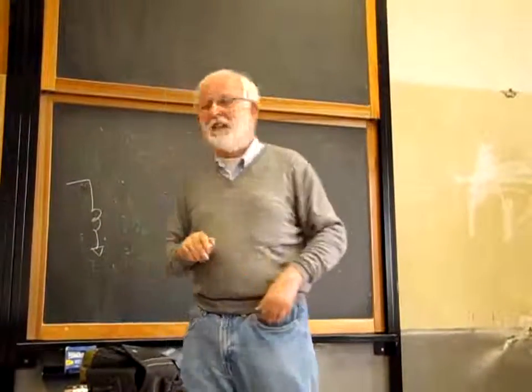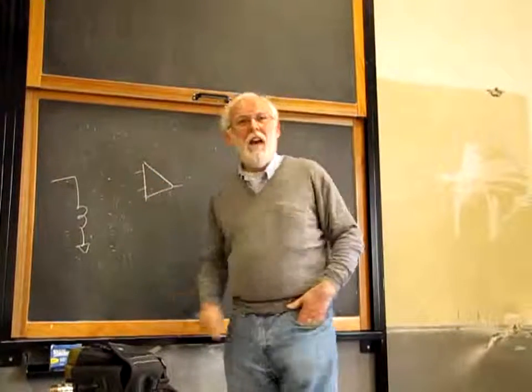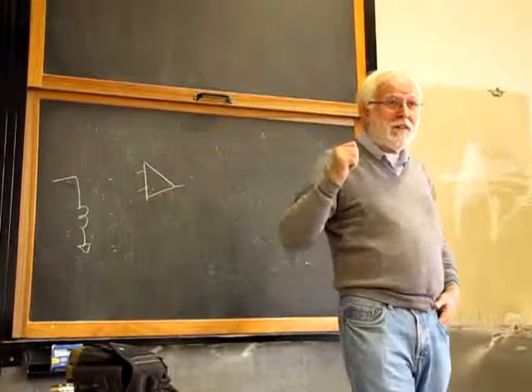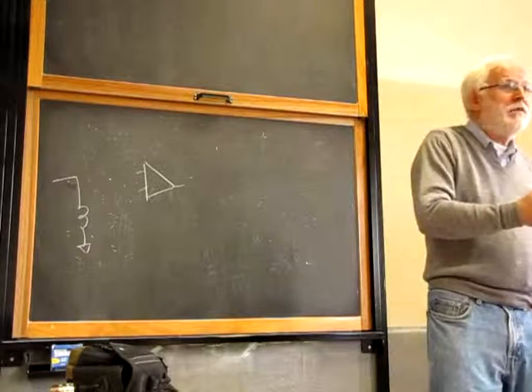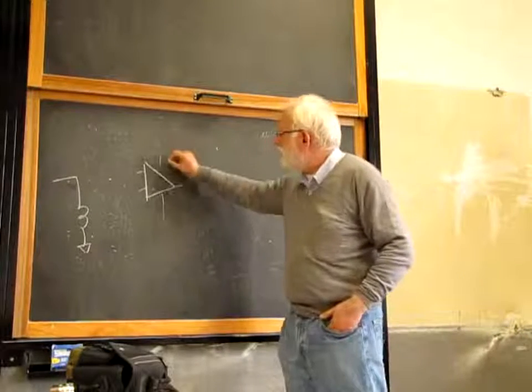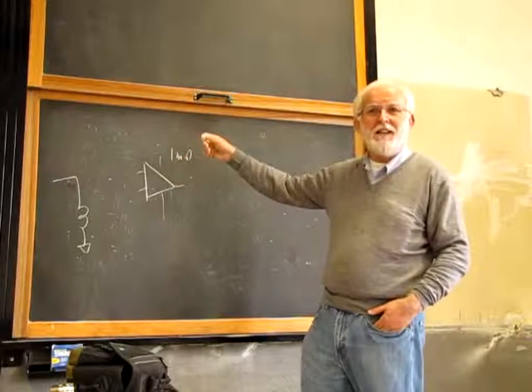The main reason is that a gyrator needs an op-amp. And we use op-amps in our circuit, so an op-amp is fine, because it takes from the power supply less than 1 milliamp of current, so we can just neglect it.